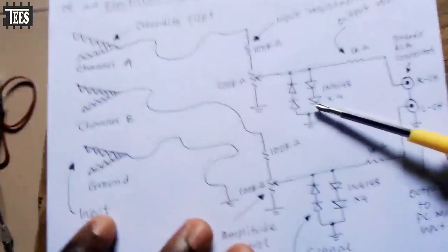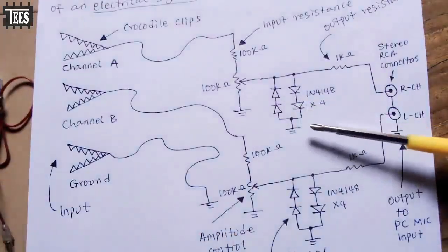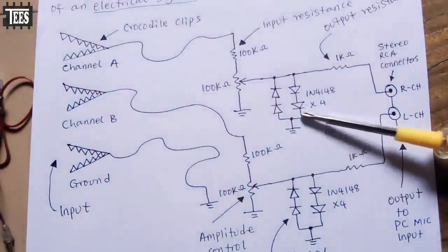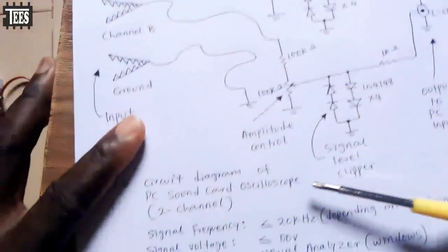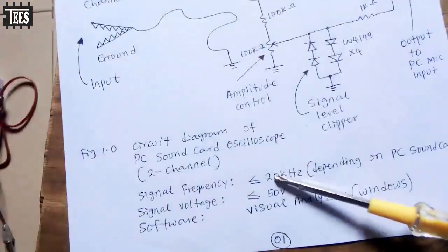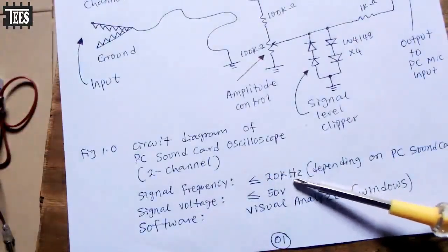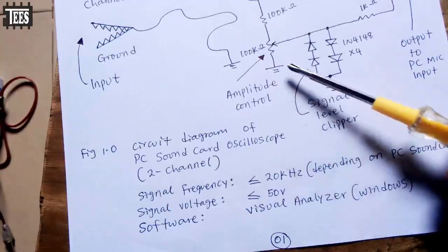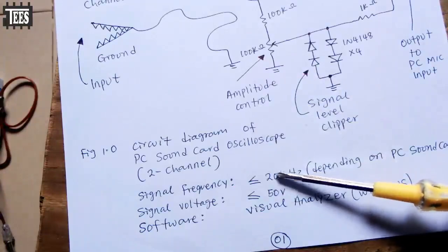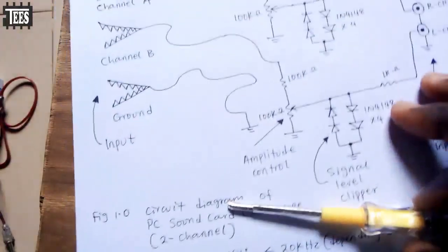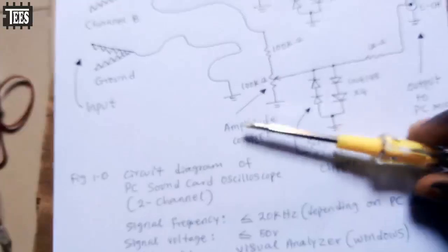And normally, the standard oscilloscopes are very expensive. So with this, if the signals that you are going to measure are below 20 kilohertz, you understand? You can be able to use it. But if the signal that you're measuring goes far beyond it, that's where you need to get a digital oscilloscope. But with this, you spend less.